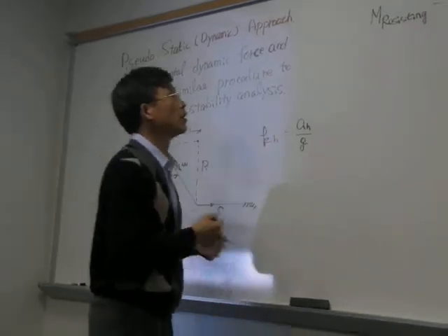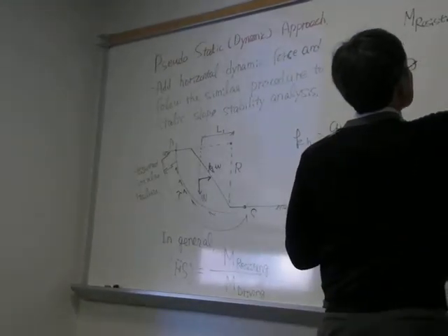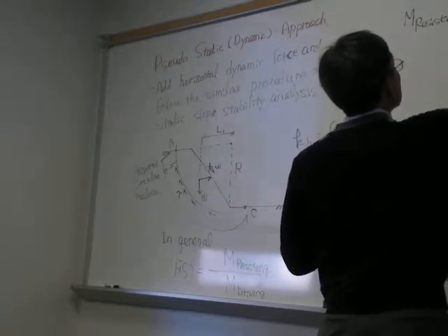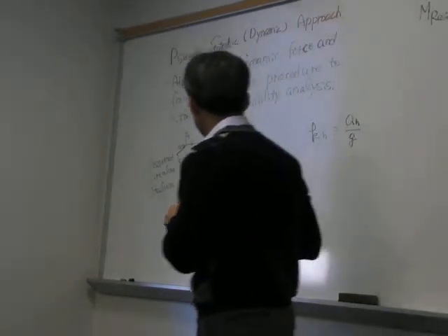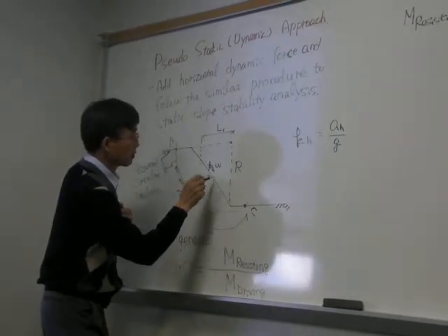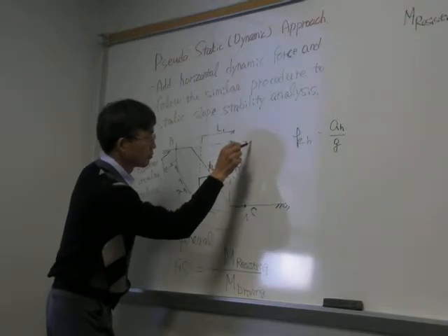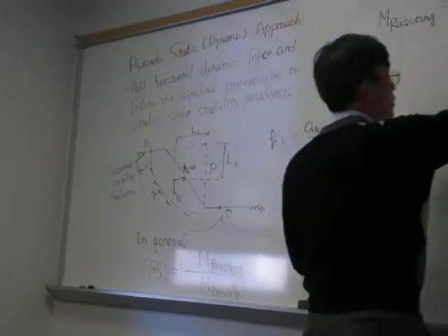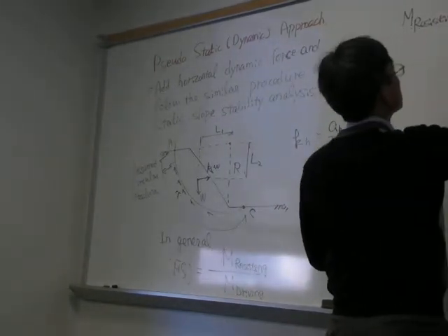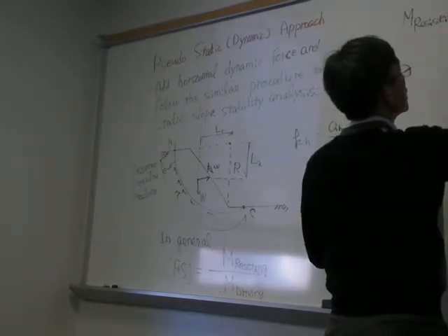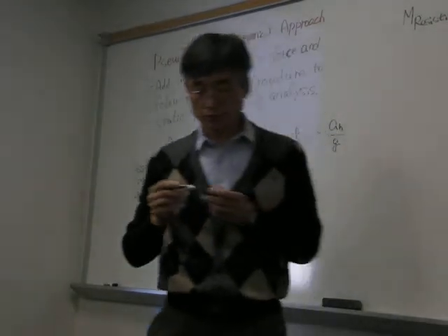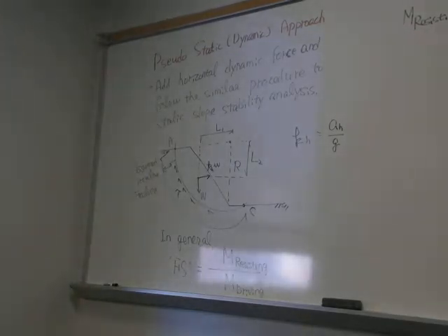So I would say there is tau times arc length AC times 1 is the shearing force, times, I would say this arm length is L2. Then it should be this one times L2. I will just rewrite it in this way, tau AC L2. That's the resisting moment.